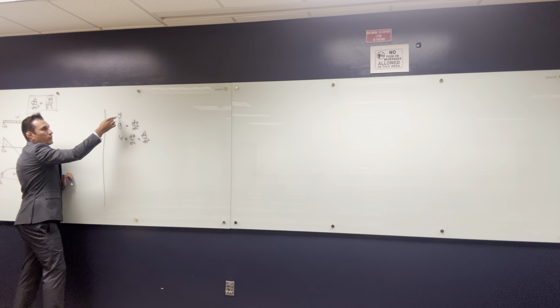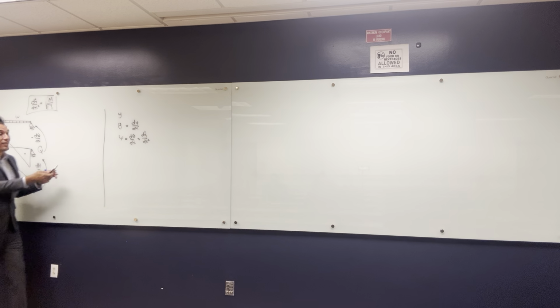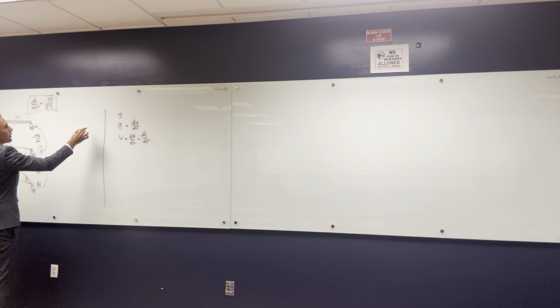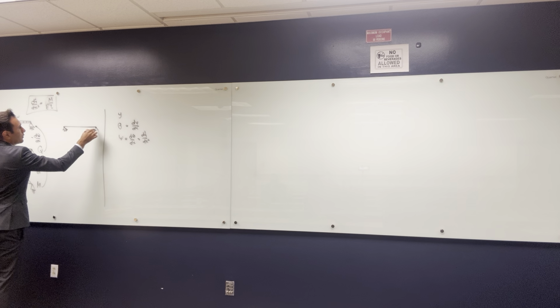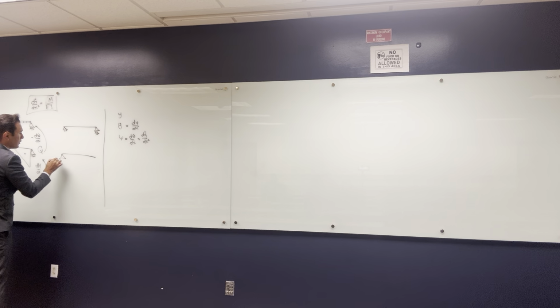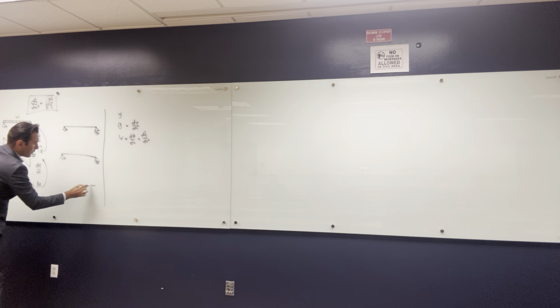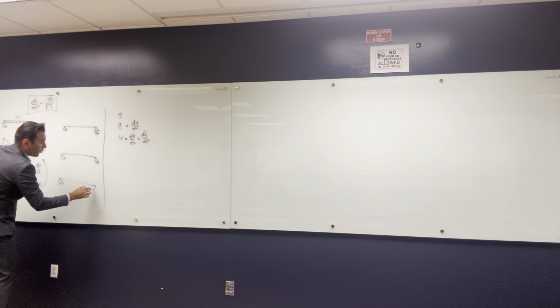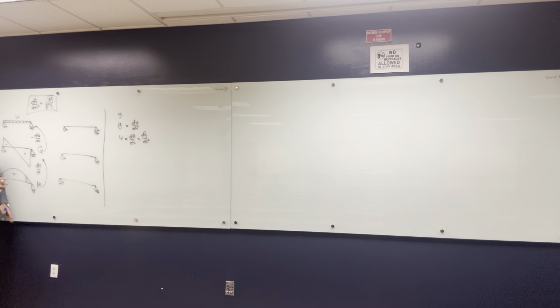Like if you want theta, you differentiate y. If you want psi, you differentiate theta. Same relationship between moment, shear, and load, right? So, let's have the three beams here. Do the same. So the conjugate beam is using this relationship between the load, moment, and shear to find y, theta, and psi. For example, if you know the moment all over the beam, you can divide the moment over EI to find psi, right? So the easiest thing that I can find is psi.